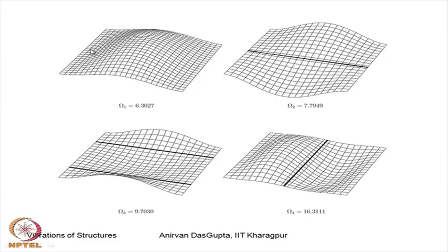You can see that displacement here is maximum, here it is not so high. Had there been no stiffener, this would have vibrated like a beam, and the displacement here also would have been as high. Because of the stiffening effect of the beam, we have lower displacement at these edges.